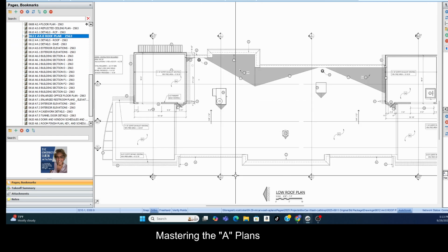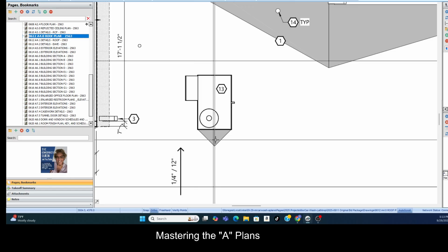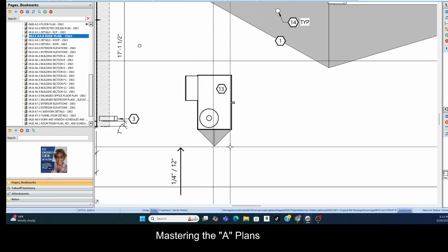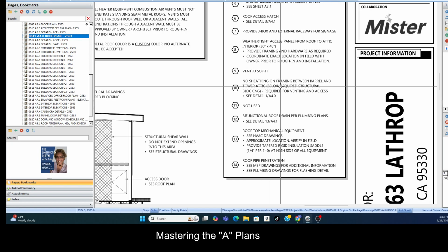The plan for the roofer, the view from above, shows you all the holes in it. And two, it's going to give us details on how we prevent holes. So, 13, let's see what it's saying for 13. See HVAC drawings. Because what is this? This is the architectural set. So the HVAC drawing is going to give you everything about the HVAC and also everything about all the construction around it and the roof curb and what is required for that.